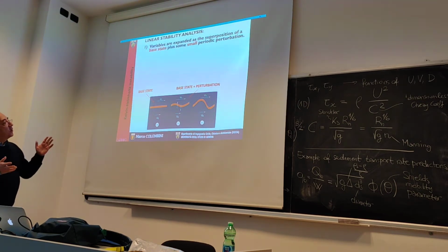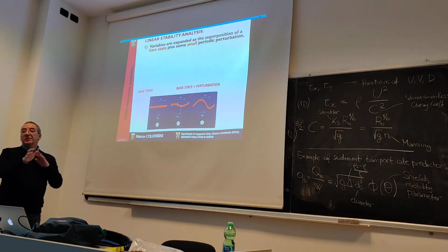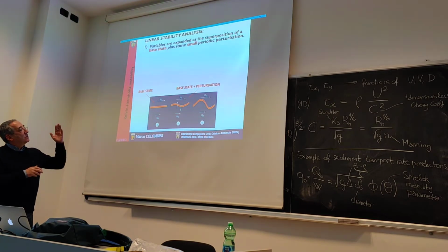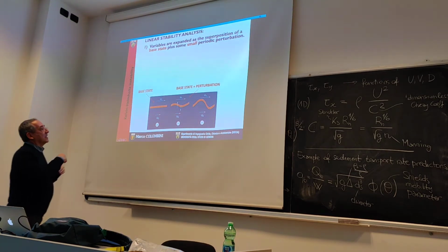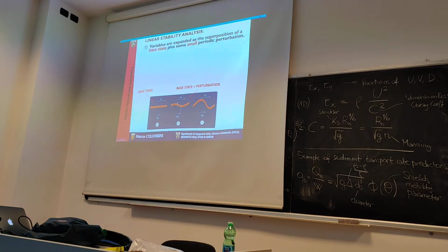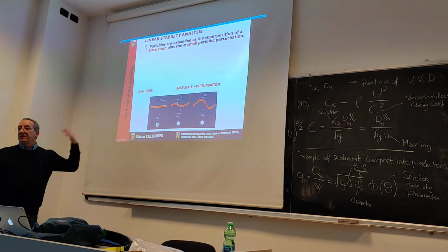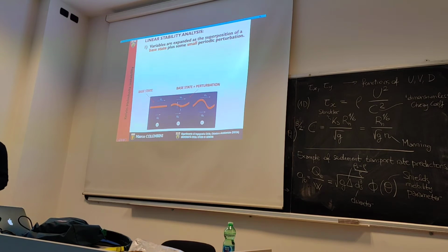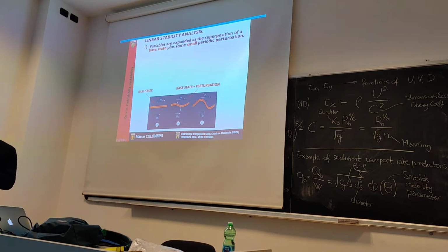Okay, so the whole idea is a way to study stability: to assume that you have a superposition of states, and in particular, for linear stability analysis, you have a base state and a perturbation, which means a periodic variation in space and time of the same function, of the same quantity, which can be the velocity, the flow depth, the free surface of a flow, but also, I don't know, the sediment discharge, for example.